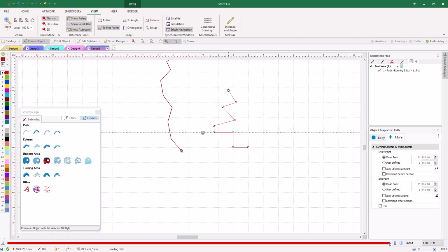When we are creating a contour, as we approach to the first node, the mouse pointer changes shape slightly. This signal indicates that, if we click, the system will create a closed contour. We can also create a closed contour using the Close Shape command from the context menu, or by instructing the system to create a mirrored contour, using the Close with Mirror Shape command.